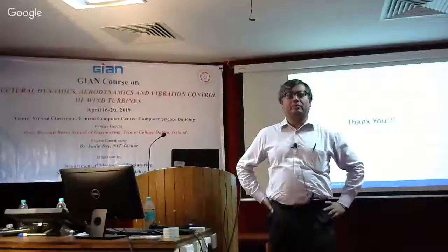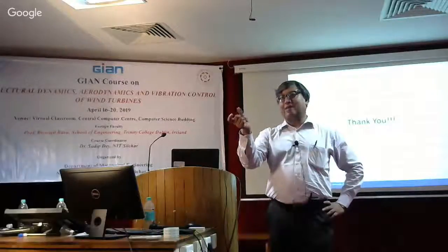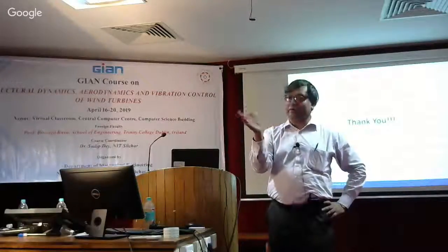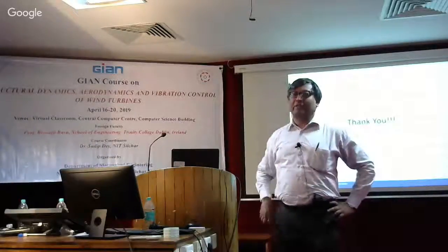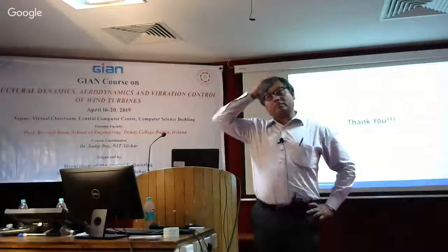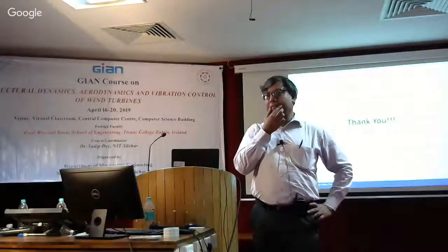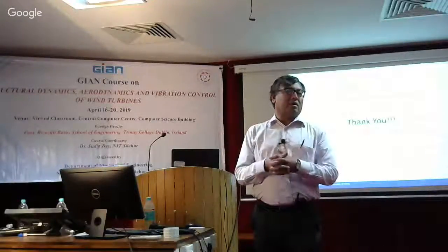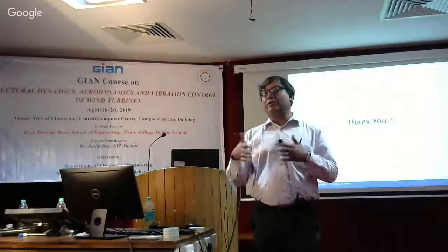So one more. Will pitch control actually reduce...? It's only in Region 2, when you're optimizing the power, that you can still do that and control the vibration. Because otherwise, if you use the pitch control for reducing the load and vibration, then you lose a bit of power. So this part of the power can be captured by using the active tendon. So one more thing you said: the generator usually has to be changed. So we can change to a higher capacity generator. Yes, it depends, and it's complicated because it depends on what kind of warranty and contract you have. So it's not easy to change the generator.